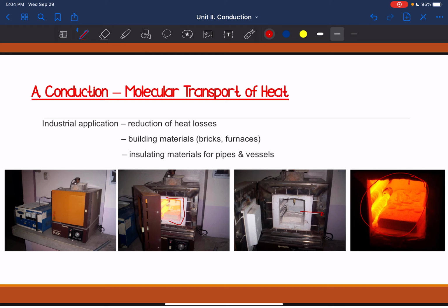So thermal insulation is predominantly used to prevent heat loss through conduction in electric, gas, or dual fuel models. Also, it is used to conserve energy, because as much as possible you would want a steady state inside the oven, so fluctuations of the temperature would mean greater energy usage.